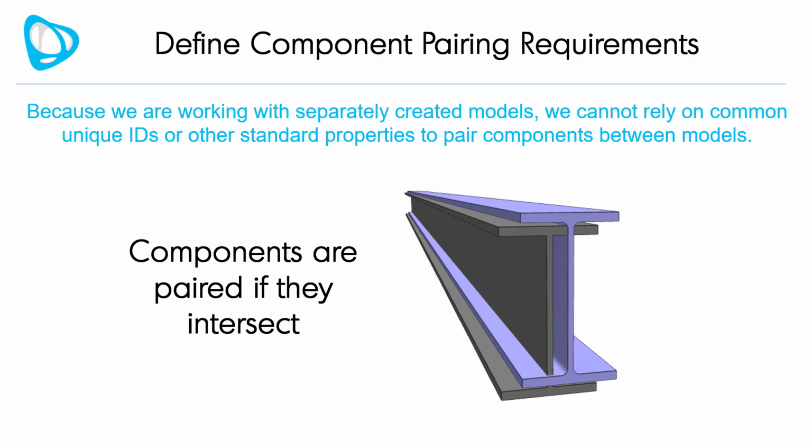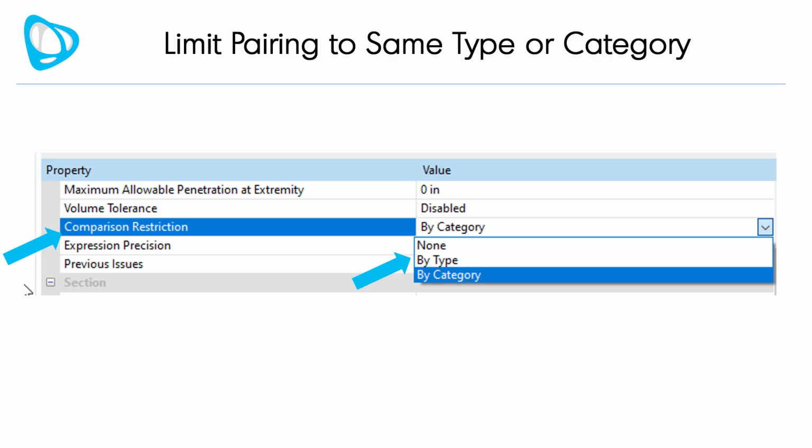Our premise is based on the fact that if components are intended to have the same intent, most likely they're modeled in the same space. So you can think of this where we're leveraging the classical clash test to be able to identify the first set of paired components. We're not calling them clashes. They're just simply paired components. So we kind of make a note of those that are pairing.